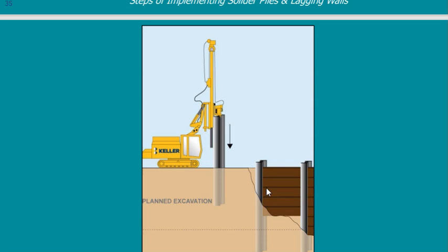And then I excavate again. Maybe I take another 50 centimeters. So what will happen to this wooden lagging that I installed at the top? It will fall down, and the remaining will be 50 centimeters. I put another wooden lagging and excavate, and put another and excavate, and put another, till I reach the depth I need.